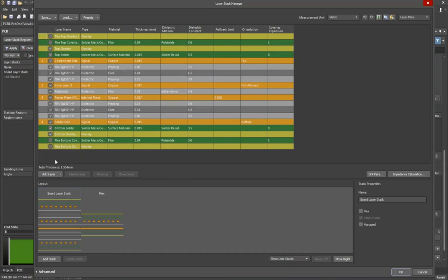So if you already have some layout on different layers, it's trying to move those primitives from one layer to another, and you see the merging layers. In our case, since this is a new PCB, there is nothing to move. So we do not need to check this in detail. We can just click OK.